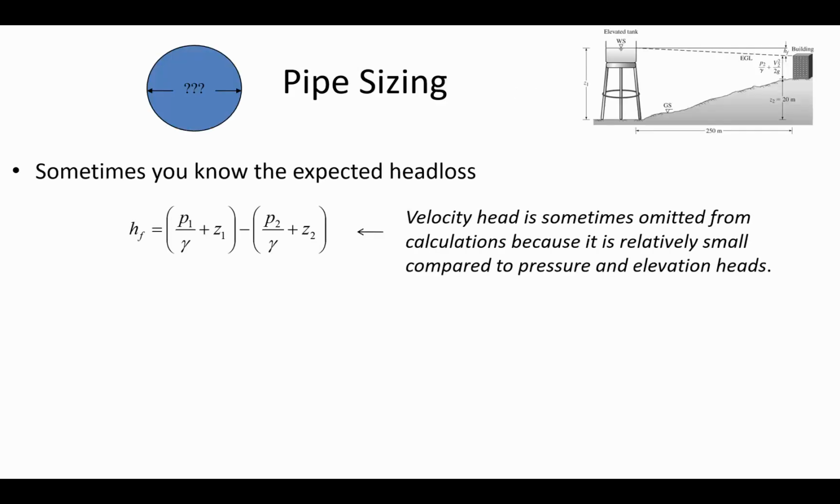Okay, now pipe sizing. The thing that we have to balance in hydraulic design is making sure that the pipe diameter is large enough to minimize excess head loss, but you're trying to make the pipe smaller because big pipe is expensive. Like if money was no object, and if we had no interest in optimization, then we'd make every pipe as big as we could find.